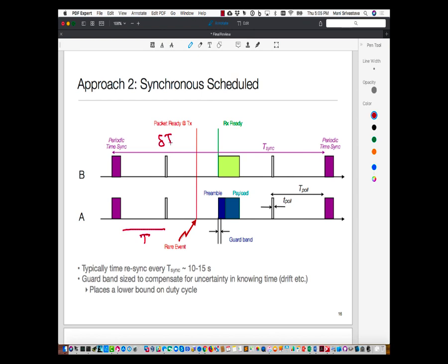And then finally, you have things like chip scale atomic clocks. As you go up, you go from maybe an error of 10 microseconds every second to maybe a picosecond per second, or even sub-picoseconds. That's the dynamic range across these technologies. But meanwhile, the energy goes from microwatts to tens of milliwatts. So delta goes more precise. I want lower delta to get better energy efficiency, but lower delta comes at the cost of the clock consuming more power, and that tension plays out again.